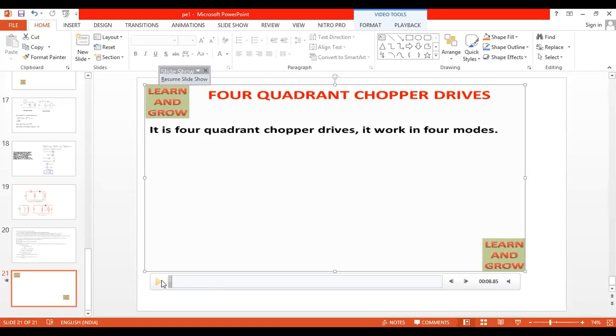Why are we supposed to study 4-quadrant? What is the meaning? If the machine is acting as a motor, it is single quadrant. If the machine is acting as motor and generator, it can be explained in 2 quadrants. If the machine is acting as motor and generator and rotating in forward direction as well as in backward direction, 4-quadrant operation is the technical word we use. 4-quadrant operation can also be done by choppers. Show me the circuit which will make the motor act as generator and rotate in forward and backward directions. We use this application in the lift system. Remember, 4-quadrant means lift.